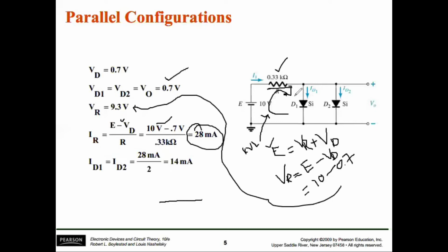This is, let's say, I1 or IR. I1 is here. This current will be moved toward this diode. There are two diodes here, and as the two diodes are similar, an equal amount of current will be distributed in each diode. Both are the same diodes with similar configuration, so both diodes will conduct the same amount of current, which will be half of the initial current value, because both have the same values, so it will be divided into two.